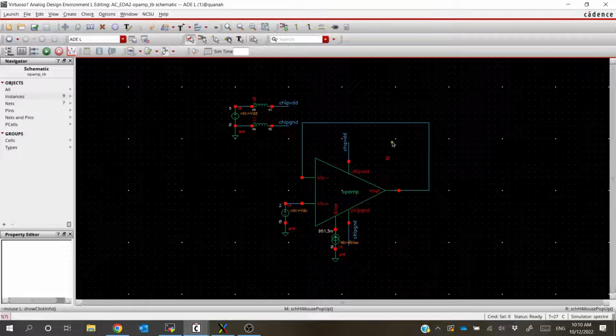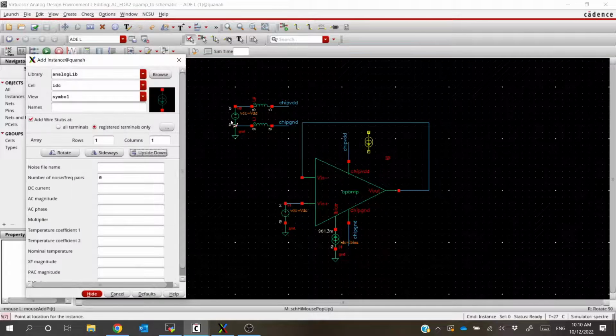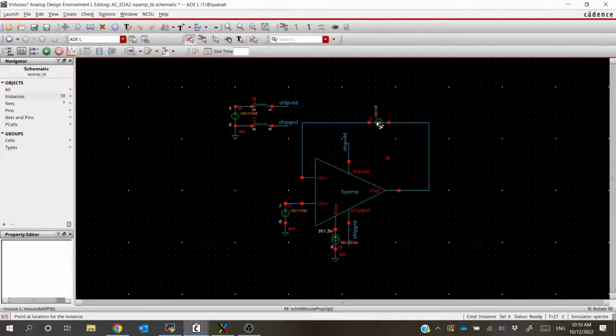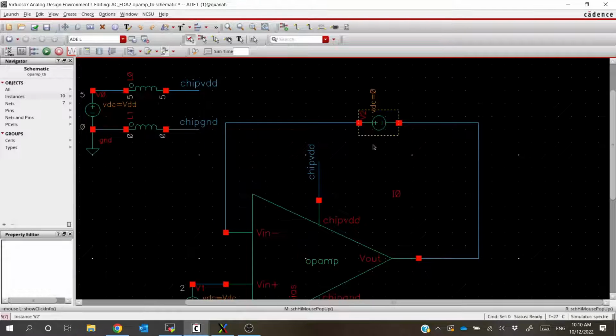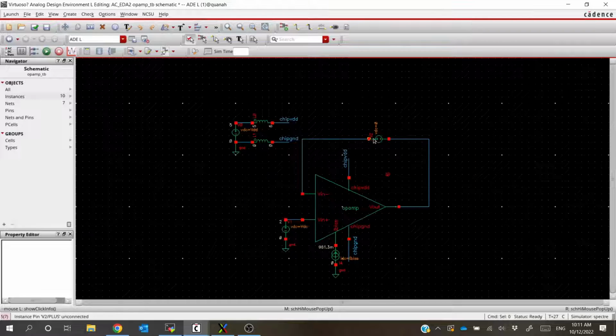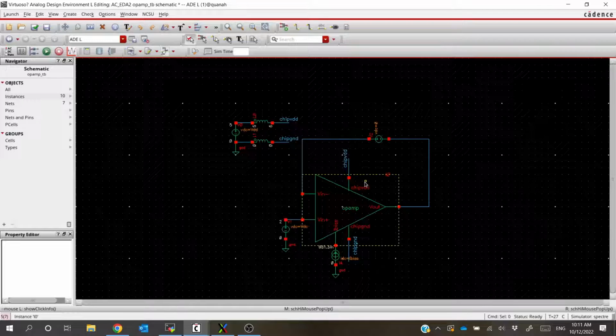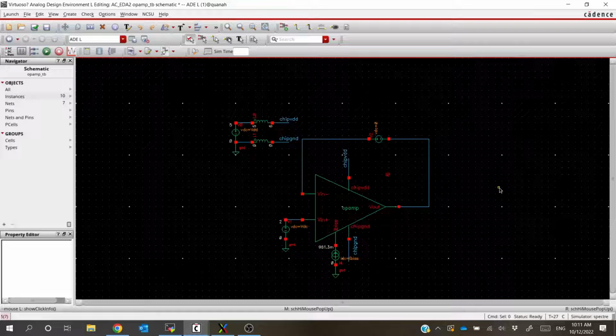The way that we can do that is to give it a probe point using a DC voltage. So we're going to connect a DC voltage in series with this feedback path. Now, if we want a DC voltage in series without it actually impacting anything, then we need to set the DC voltage to be 0. So it's pretty much a short circuit, and we can place it in this feedback path and break the loop here. Now we have a DC voltage of 0, so it's almost like it's not even there. It's pretty much just a short circuit, but this gives us a point to click and probe our feedback loop to actually measure the loop gain and measure the stability. So I'll save and check again.